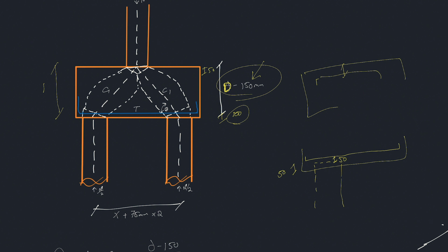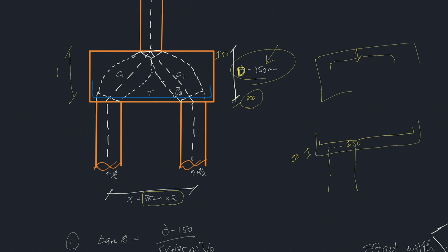And another thing is the distance between the reactions. It is the actual physical distance between the piles, but you also have to add eccentricity allowances, because this one might be out and this one might be out. There is a very small statistical chance this is going to happen, but since this is the tolerance, we need to allow for it in our design because it can happen.